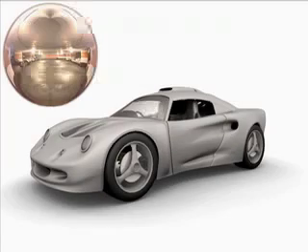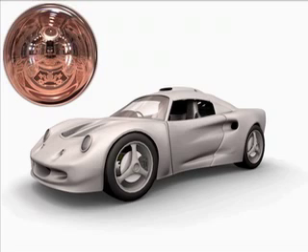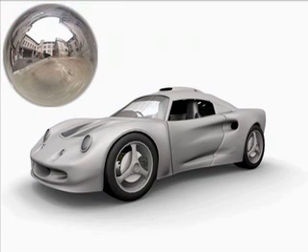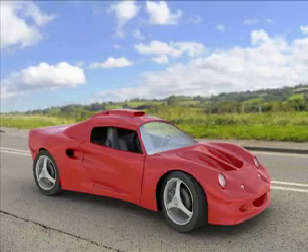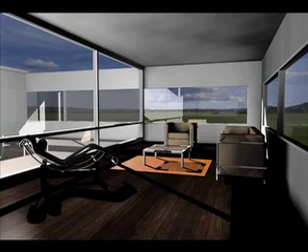All the scenes you see here were rendered using a single HDRI high dynamic range image as an environment light. So you get not only the environmental reflections on the surface, but also the entire scene is lit by that single environment image that has the lighting data stored in the image format itself. And if you need, there's a radiosity version of formZ that can accurately pre-process and calculate how the true light intensities are bouncing around within the scene.